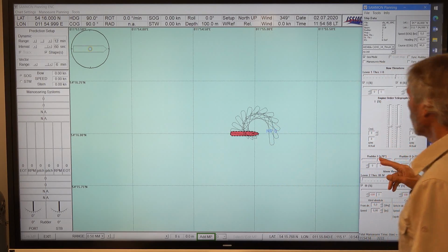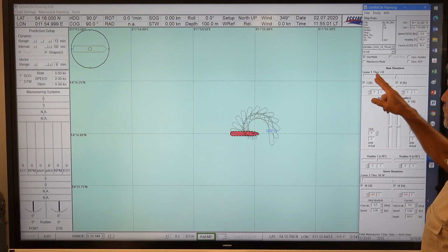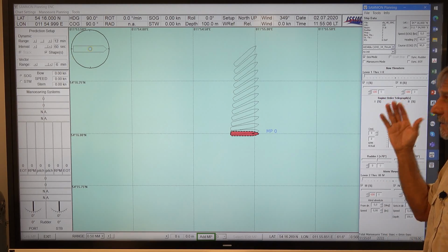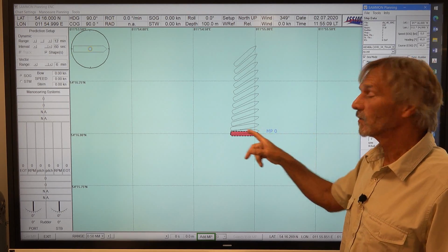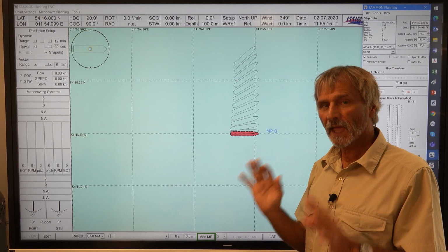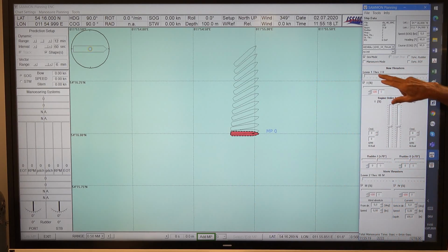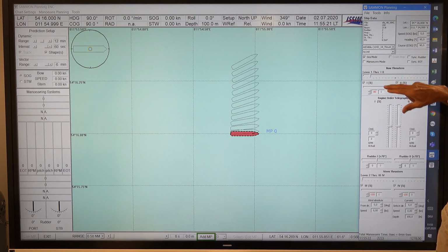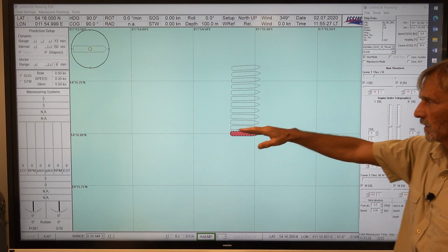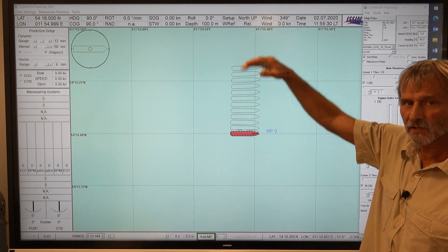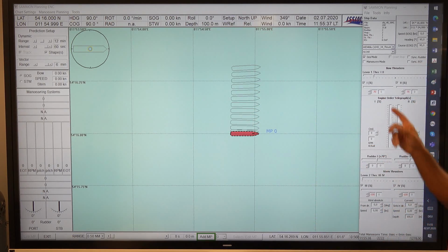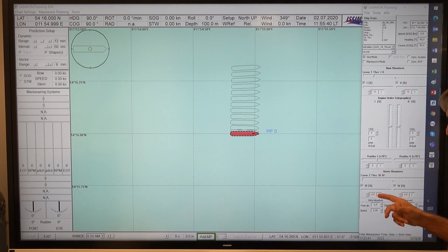And if we want to find the balance against the wind, then we use the bow thruster. If we use the bow thruster with 100%, then we see the bow thruster is stronger than the stern thruster. So the bow will move against it, but we want to achieve a parallel drift. So we have to reduce the bow thruster to 90%, to 80%, to 70%. So what we see here is you will really work in parallel transverse motion, and every shape is 1 second, and the bow thruster is 70%, the stern thruster is 100%.